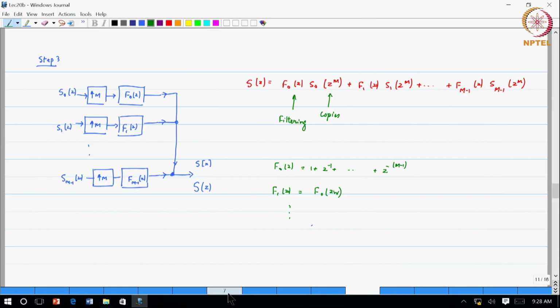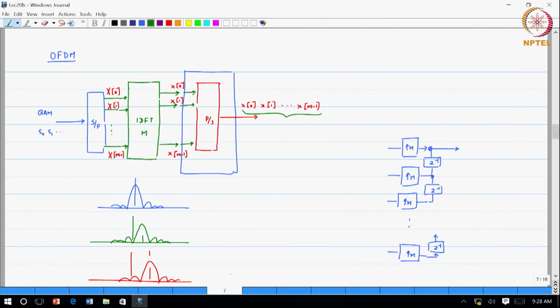And that is where we said that the transmitter portion of the OFDM is actually generating a frequency division multiplex signal, and it is beneficial for us to think of what those filters actually look like, and those filters are these shifted versions of these filters. And what is it that is being applied to these carriers? Those particular symbols, QAM symbols.